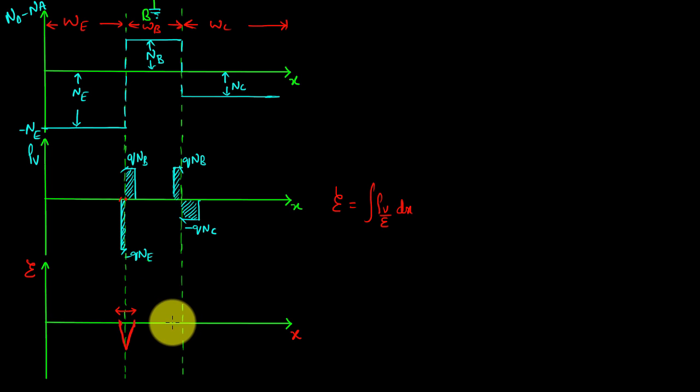And now once we cross this point, till this point the area would be 0. So after this it would be positive. So we are adding positive value. And as we go forward, a negative value gets added. So this electric field decreases, and once we reach this point, it would be 0. Because this area would be equal to this area. And this width would be equal to the depletion width of the collector junction.